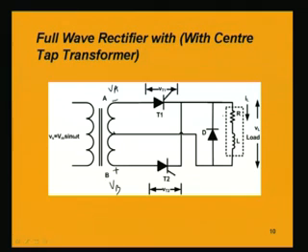So, the load current which is flowing, IL is the load current, it will be contributed by the diode current only. The current will not flow through this thyristor, but we will be having a load current which is contributed because of the diode.